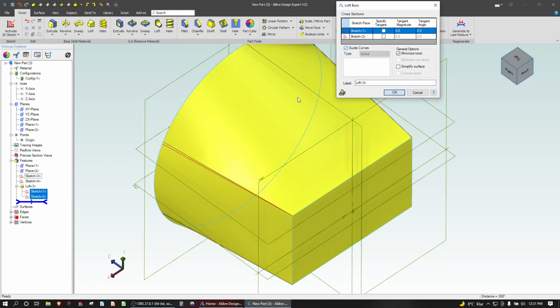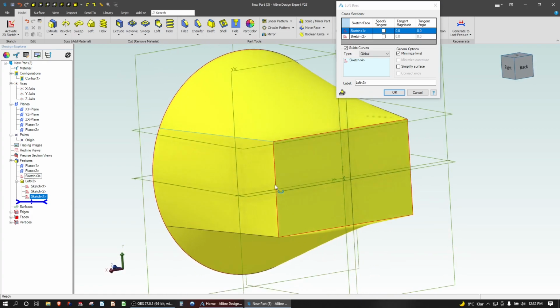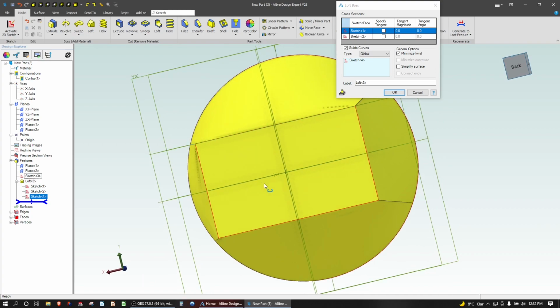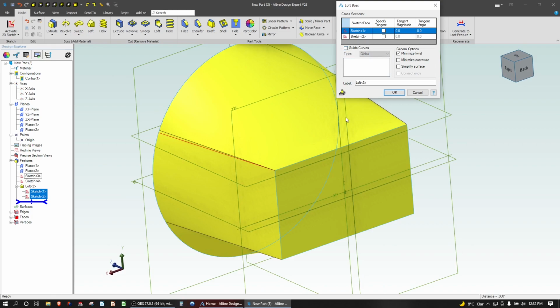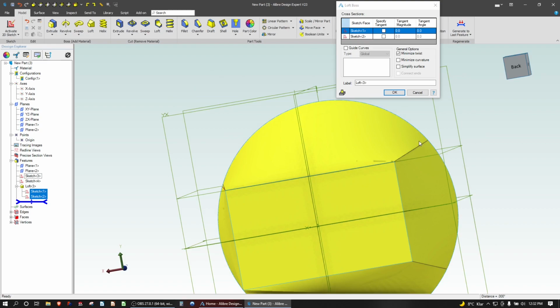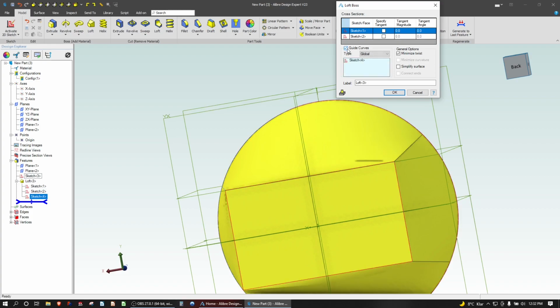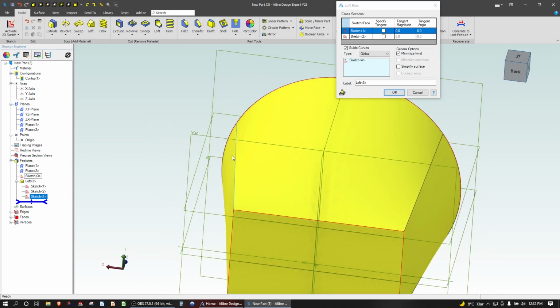And let's use a guide curve to import our straight line, right? So you can see we now have a straight line that we're dealing with. And this straight line thing, if I get rid of my guide curves, changes a few other parts of the sketch, right? So if you watch this line right here, when I click on a guide curve, it's changing some of the other lines. So note that that is a thing when you import a guide curve. It doesn't just change it locally. And we're going to talk about how to work around that.